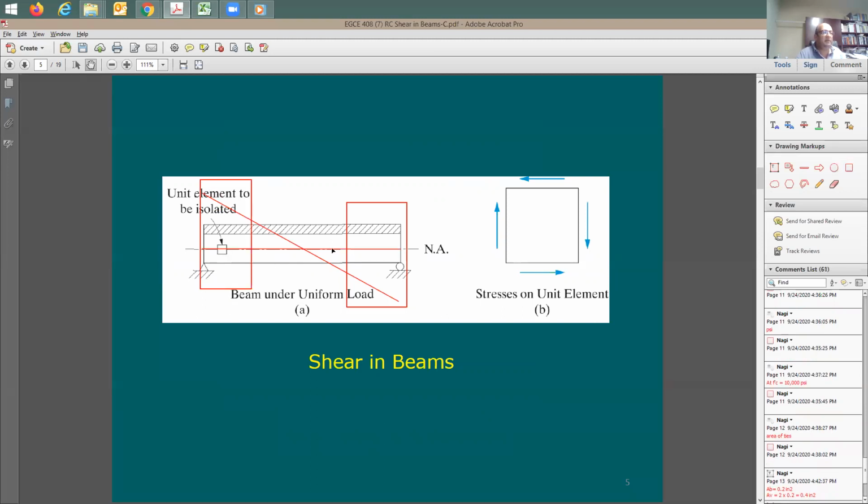How about the middle area here? Well, shear is not going to be that much. So if you'd like to play with the spacing of the ties and the number of legs, in this section and this section, the areas of maximum shear, you're going to have lots of ties, as expected. But this area here, close to almost no shear, you cannot put that many ties. I can put maybe the minimum as required by code. Does it make sense? Yep. Okay, all right.